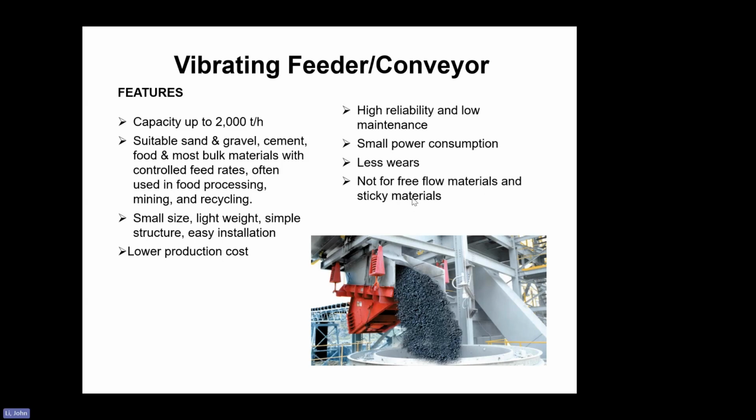But it is not suitable for free-flow materials and sticky materials. If free flow, like fine sand or beads or beans, it will be an uncontrolled flow, so it will flood the downstream equipment. And it cannot be used for sticky materials, they will stick on. When you vibrate, it will compact the sticky materials, so they cannot handle it.